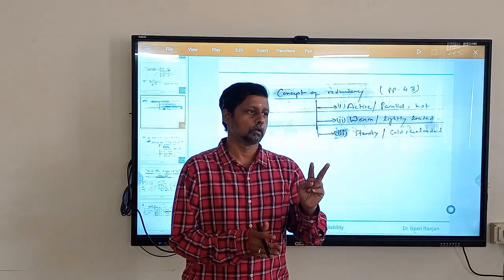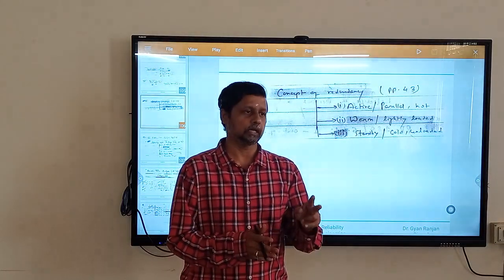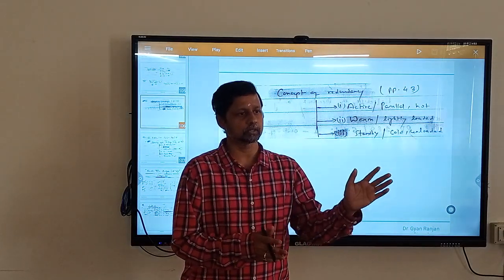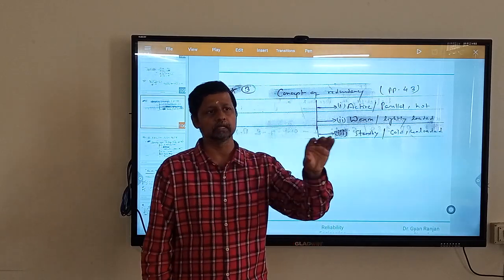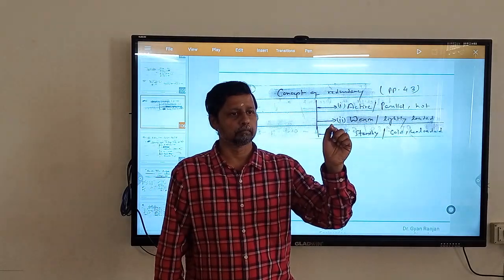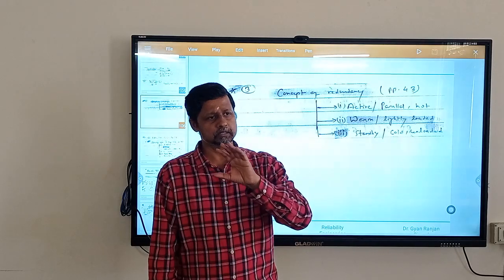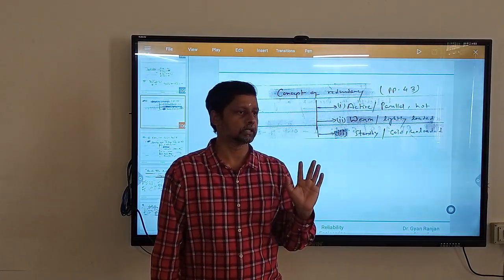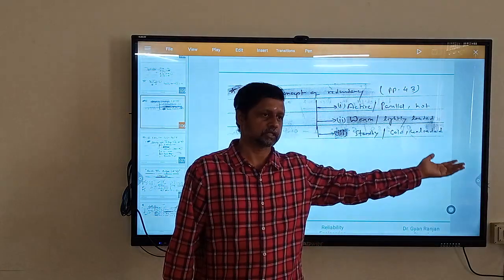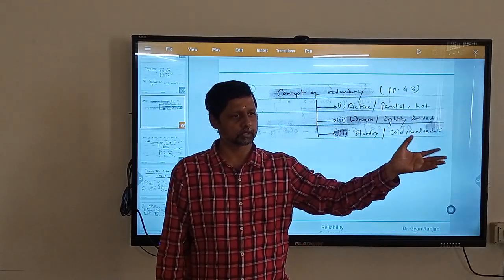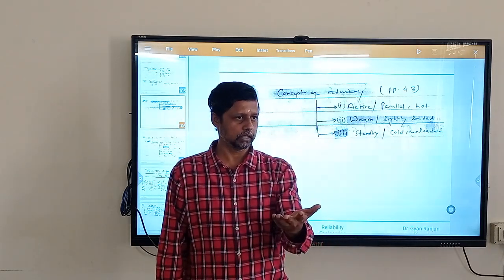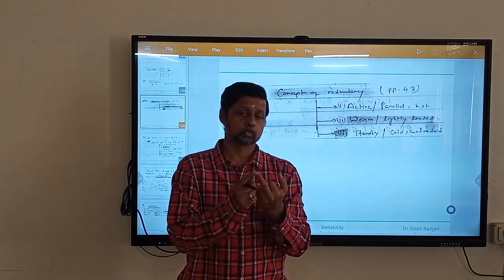It will come with a feature that if the feeding process is timely over by 83B, either it is fully consumed, that is one scenario, or number 2, the 83B line is facing some problem, requiring maintenance, or it is operating normally. Whatever the capacity of 83B was, it has been already filled. Then it has to go to the next stage, that is depressurization. No more active operation, so it should go to standby, and the standby one should swap its position to active. Getting my point? This transaction should be done in real time.